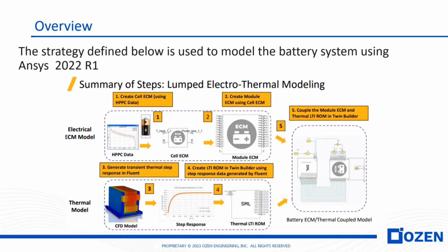Then we're going to generate a thermal step response in Fluent. Then, because CFD is costly, we don't want to keep running CFD in a systems type model. We're going to convert this response into an LTI ROM. And that essentially is going to generate really quick thermal responses within our systems model within TwinBuilder.